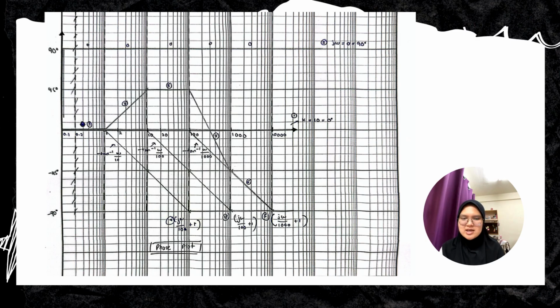For this slide, the slope line indicates the phase transition region caused by the presence of a pole. The flat section indicates an almost constant phase angle. If more than one pole is present, the phase effects are combined, resulting in a larger phase drop, for example, minus 180 degrees. At high frequencies, the phase angle becomes nearly constant at a negative value, indicating that the output signal lags behind the input signal.